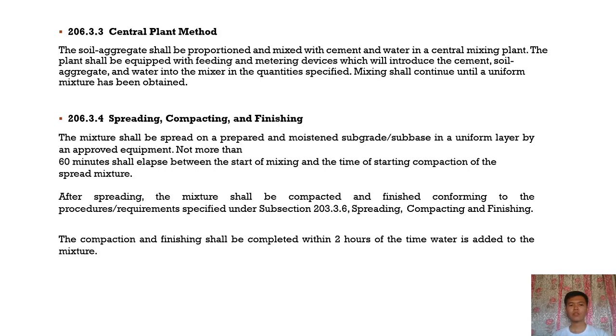After spreading, the mixture shall be compacted and finished conforming to the procedures or requirements specified under subsection 23.3.6, spreading, compacting, and finishing. The compaction and finishing shall be completed within 2 hours of the time water is added to the mixture. So, it is still the same, the time limit for the concrete before it is hardened.